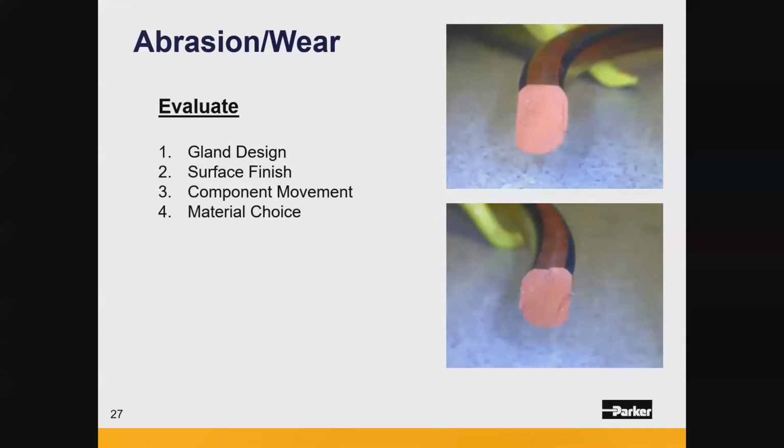To prevent this from occurring in your gland or in your sealing application, you definitely want to consider your gland design. For dynamic applications, we recommend, for instance, a reduced amount of squeeze or compression compared to what we would for static applications.